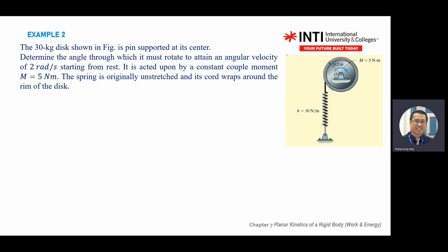For the center of mass, IG, you refer to the table. If you have an external point outside from G, I label as O, you have IO equal to IG plus M D squared.